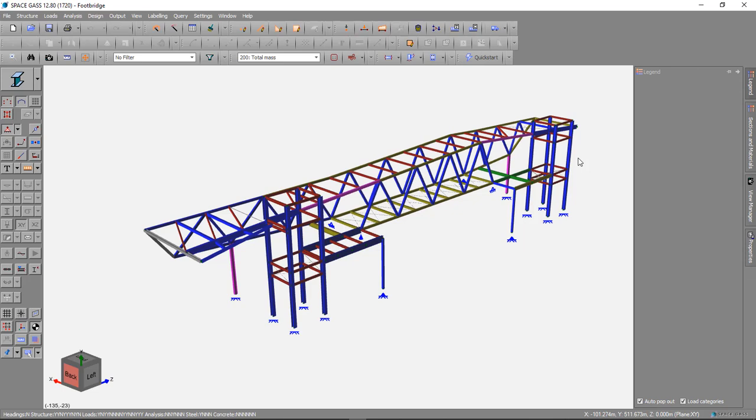A time history analysis, which is also known as a transient response analysis, depends on you having some ground motion time history data for the site at which the structure is being designed. This method, although very accurate and efficient, isn't used as much as the spectral analysis method because getting that ground motion data for your site is quite difficult sometimes, or most of the time. I will demonstrate the time history method briefly at the end of the webinar though, just to show you what's involved.